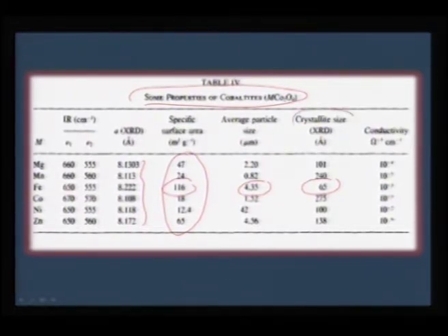The crystallite size that you see from XRD is a true measure of the particle size, close to whatever you learn from TEM. So, you can see here it is roughly of the order of 6.5 nanometers, and because this is so small, the surface area is very large. And we can make several comparisons of that.